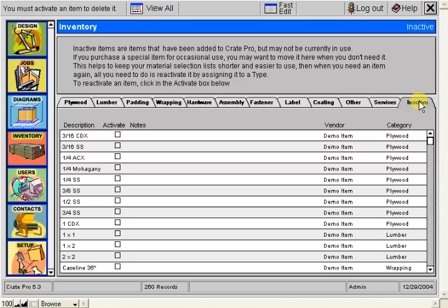Now for the second example, assume you have an old design that uses the 1/2" 5-ply and the customer places a new order for the same crate. In this case, you would make a copy of the existing design record, then select the option to update the times and prices from the inventory file. When you do this, CratePro is going to look for that 1/2" 5-ply in the inventory and not find it. The result in this case is probably worse than in the first example.